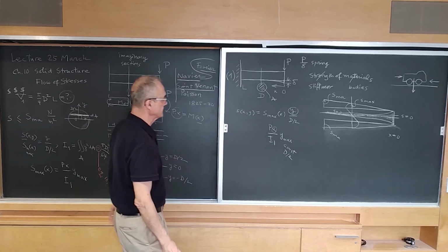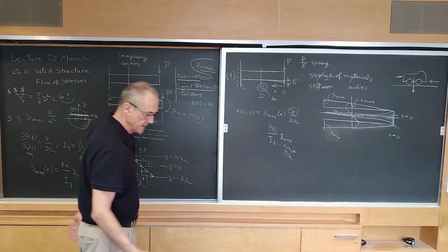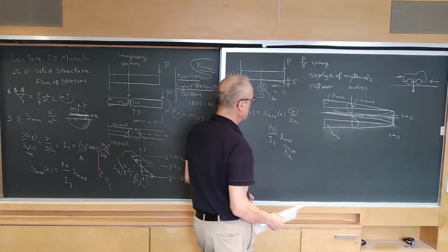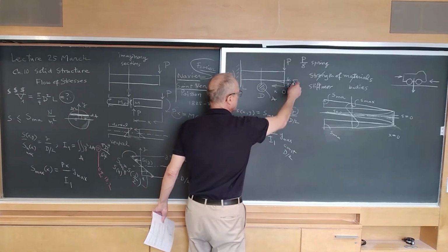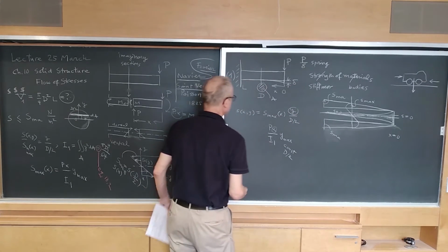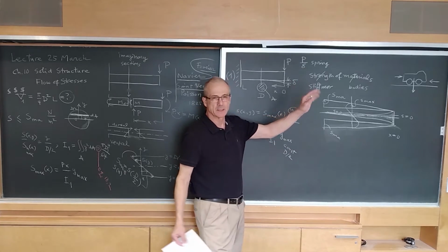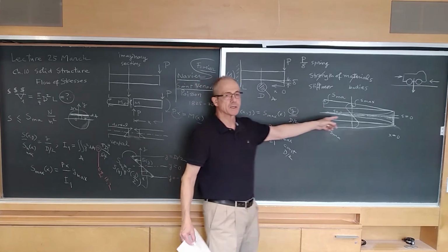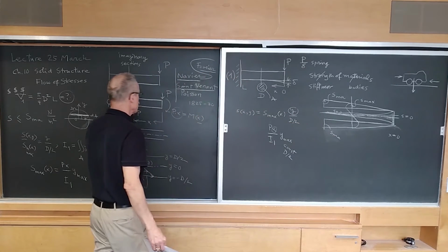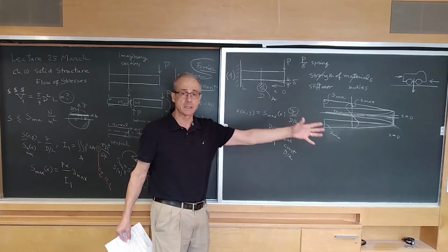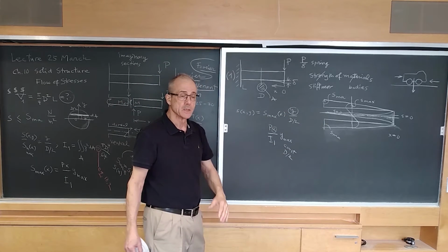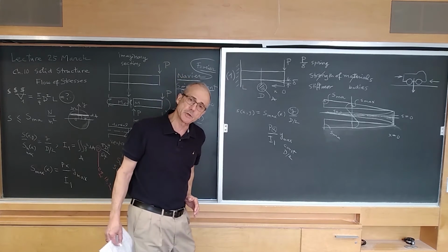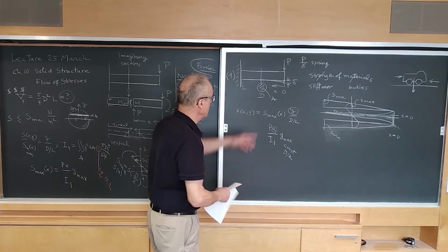Now, there is a general formula in strength of materials which yields the value of the deflection of the tip. The deflection of the tip is an aggregate result of the stretching or compressing of all these fibers inside the body. Half of them in tension, the other half in compression. So the volumetric integral of those elongations or shortenings is the value of delta.